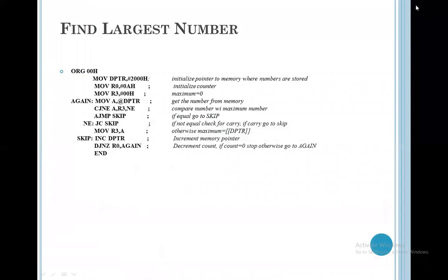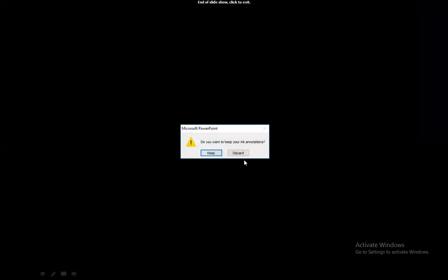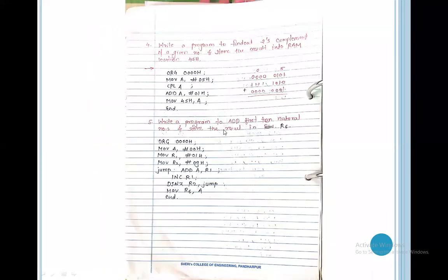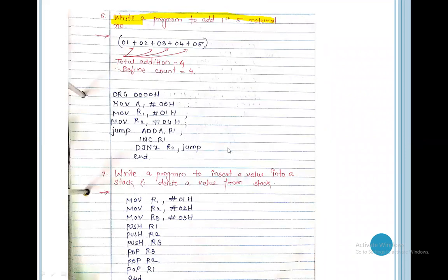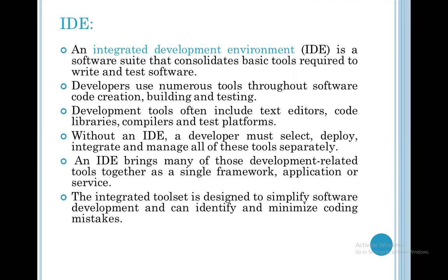And the last lecture's program: move A, #05h, CPL A. We discussed two's complement in the last lecture. These last two programs we will discuss in the next lecture.